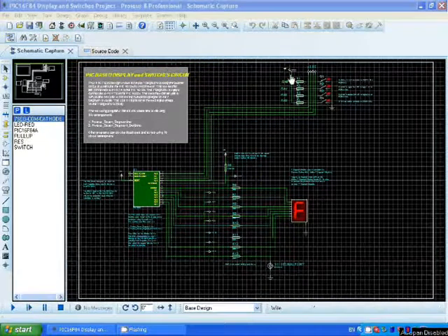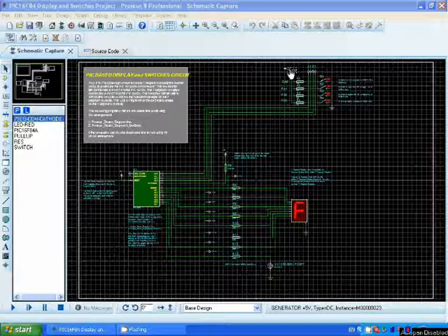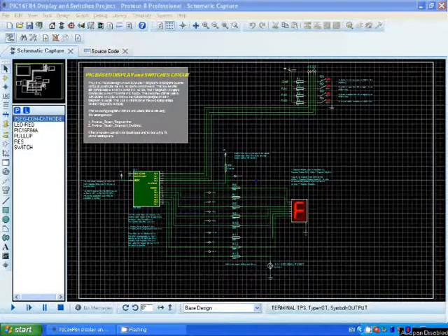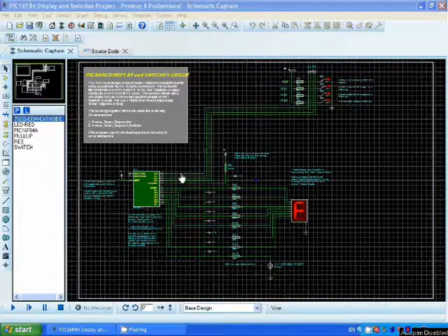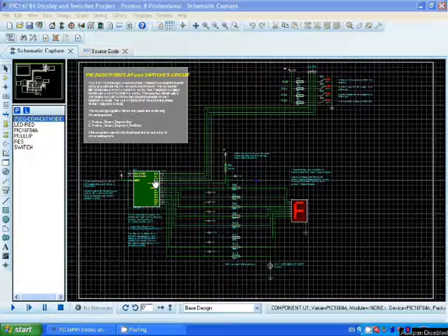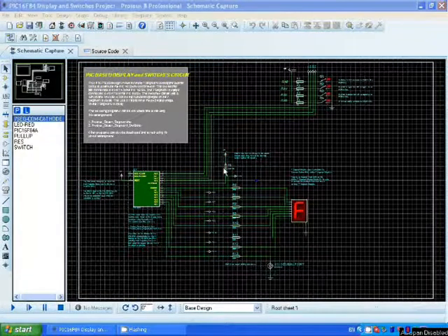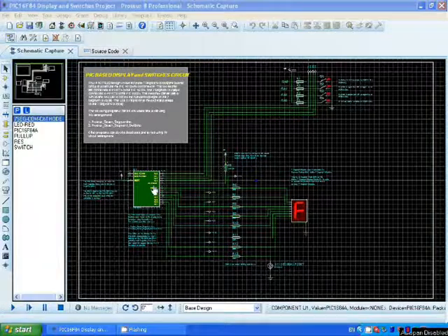We have 4 resistors, and the 4 resistors of course are tied up here to a DC power supply of 5 volts. We have test points 1, 2, 3 and 4. So this part of the circuit, which is wired down here using these 4 lines to port A of the PIC microcontroller, is completely unchanged. We have our 5 volts, our pull-up resistor R5, which is also wired into port A. So this whole top part of the circuit is the same as your previous simulation.